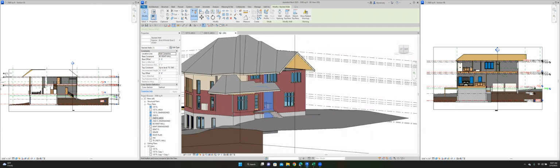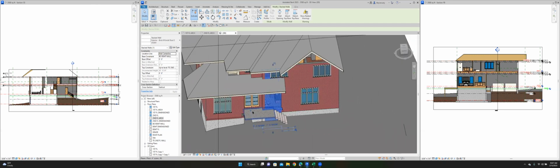Shift key down, push the mouse wheel straight down, rotate this around. That's kind of what I wanted. One of the other nice benefits is that it'll make my porch a little bit deeper right there at the front door and at the boundary. Back to the first floor, and then I want my porch to follow. We draw that perimeter here. We can extend.